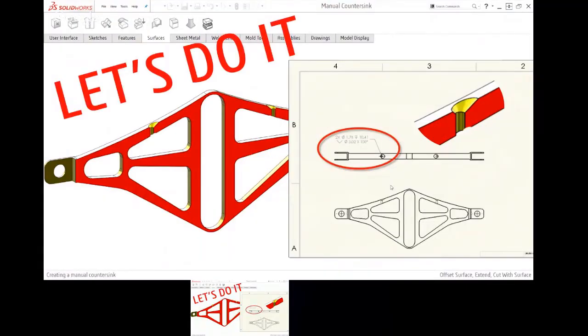All right, so a pretty good practical, more of a machine design type application. Remember that the specific application here is I really want that whole call out, so I wanted to use a hole wizard feature. To me, that was more steps than just doing a revolved cut, but here drafting accuracy was paramount. I'm more of a fan of direct to print and model-based definition, so I probably won't use that very much.